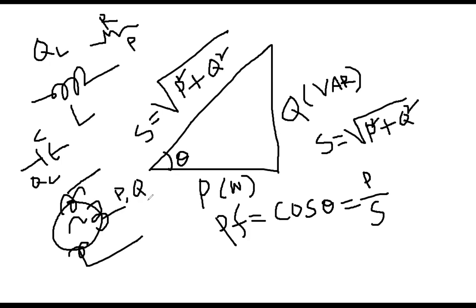So we have to try to compensate this Q. We have to try to minimize the value of Q. You can't avoid it because it is coming from the system. Not just the generator, along the line, those cables are basically inductors, mainly inductors. They have little resistance. Think about the transformer. That is basically the coil, magnetic coil, primary side, secondary side.